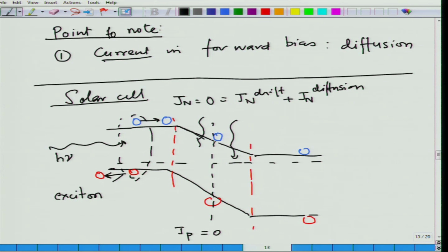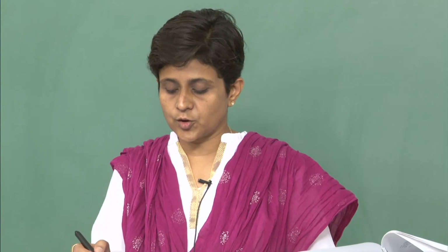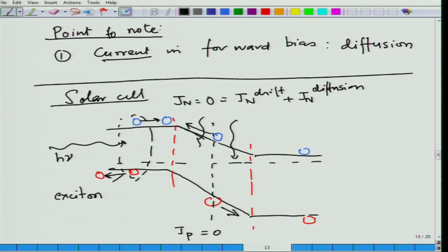So, if this electron hole pair is created in either p or n type, it will not be collected by the two ends. On the other hand, if you are in the field area, what is happening is this electron, because of the field, is going to be moving up and this hole is going to be moving down, and as a result you will generate a current in the material. Same thing will be true for the exciton if it is generated in the n type. It is not going to break open and be collected by the two ends.